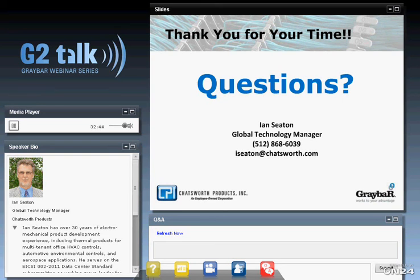With PDUs, most PDU manufacturers now are offering at least one SKU that is intended to operate at higher temperatures, and that's a spec that you need to look for going forward if you're going to take advantage of these kinds of economizers or economies, so that you're speccing PDUs that will operate in those temperature ranges.